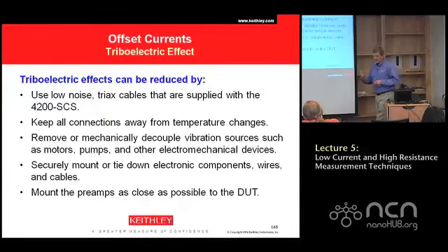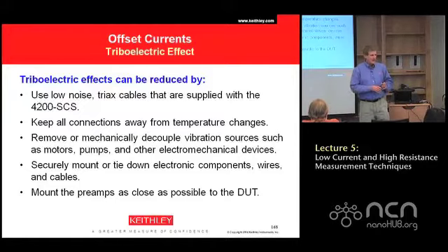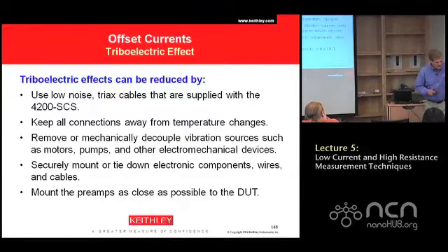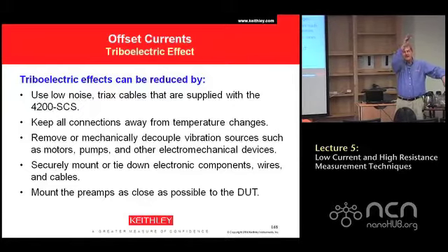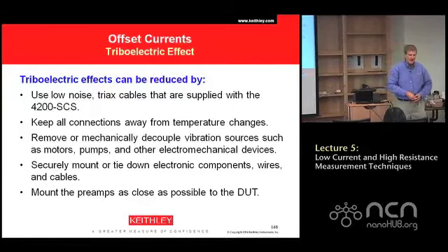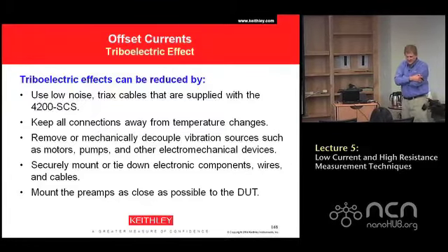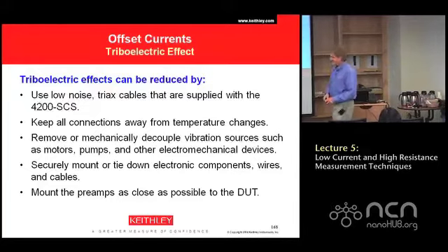So it's best to tie down your cables. Now remember, this is if you're doing really sensitive measurements. My rule of thumb is 10 picoamps. If I'm trying to get stuff under 10 picoamps, I need to take care of getting the cables tied down. A lot of people will take the instrument and set it over there and loop the cables over here and hook it up to the probe station. So that cable is sitting there and maybe the air conditioning's blowing on it a little bit, or people walk by. The one I really like is when your lab partner stands there and you're waiting for the measurement because it's a low current and he's kind of fiddling with the cable. Just because you're standing there bored, and you're going, yeah, you just blew my measurement, man.